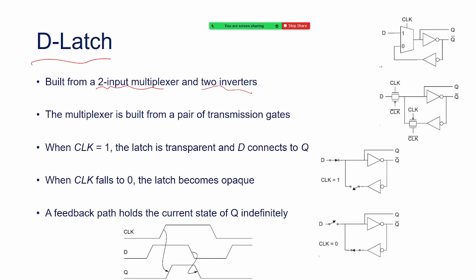So when I apply clock here, I have its complementary, and I have applied clock here to the PMOS and it's complementary to the NMOS. See, these two clocks are reverse here. Here to the NMOS I am having clock, and to the PMOS I am having the complementary. But here in this pass gate I am giving complementary to the PMOS and normal to the NMOS. It's just to make the switch on and off one at a time. We'll see that in this bottom network.